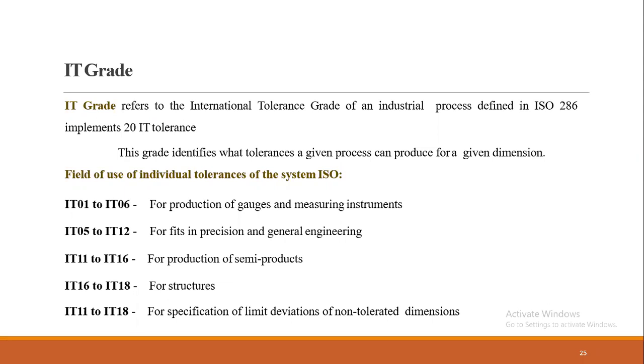IT05 to IT12 for fits in precision and general engineering. IT11 to IT16 for production of semi-products. IT16 to IT18 for structures. IT11 to IT18 is used for specific limit deviations of non-tolerated dimensions.